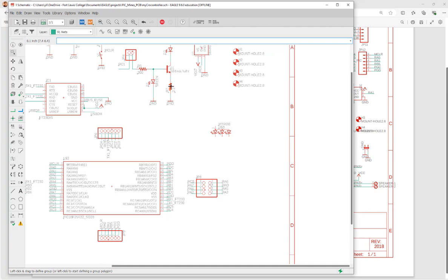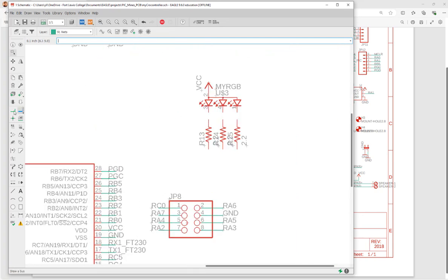You can directly copy and paste the resistors. Just any one, doesn't matter, since we can always change the value. It's the same footprint, okay? Do this and make the connections. Remember, there's a header pin on it. I think it's really important because eventually we are putting jumping cables to it in the testing phase, right?